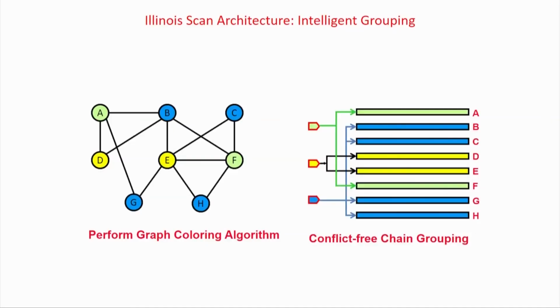So basically you think that A, B, C, D are all these scan groups or scan chains. Basically in this case there are 8 scan chains. So each scan chain will be basically your node, and I have a point in between A and B. So there is an edge between A and B if they are conflicting. So A and B are conflicting, so I have an edge, so that A and B cannot be supplied patterns by a single pin because they are conflicting patterns.